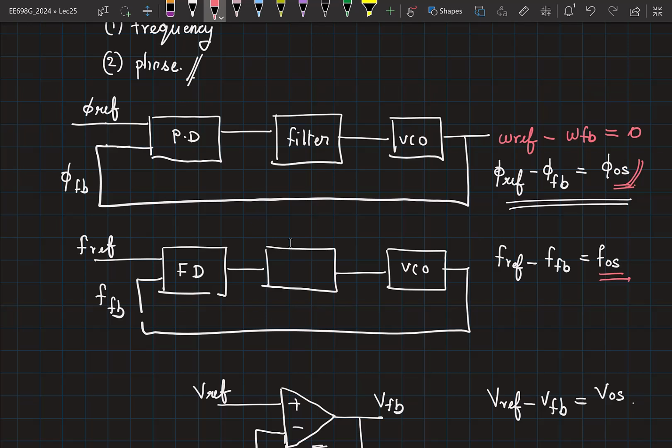If you are running one long simulation, for that given condition, it was not changing from cycle to cycle. If it was changing, then it's jitter. Now it could be a deterministic jitter if the DLL is going back and forth, but then it is called jitter.